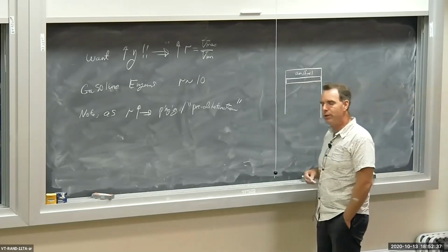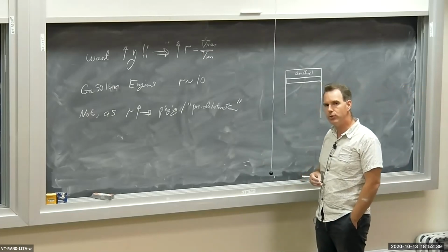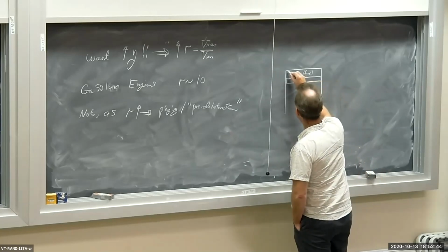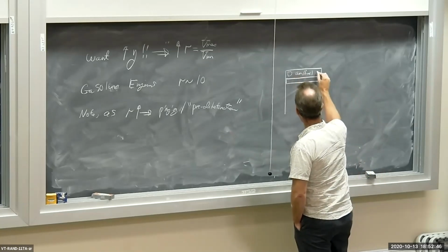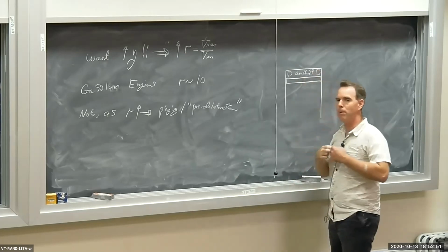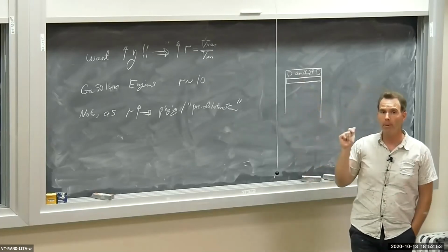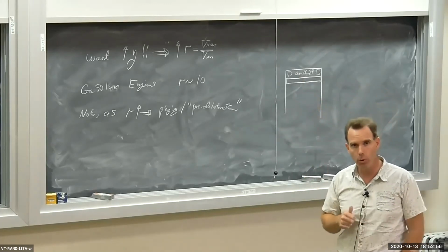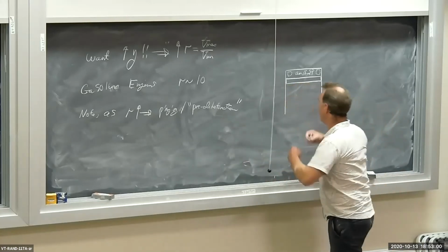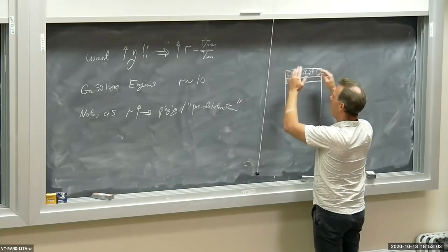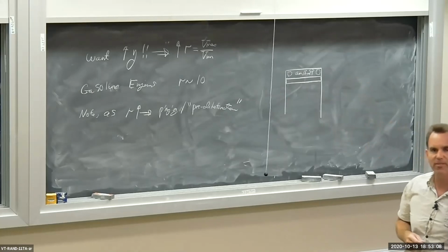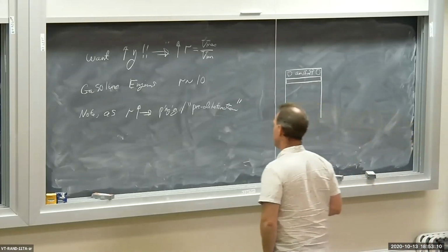If the air-fuel mixture starts to burn or release heat or explode, if you like, in multiple places, so you've got a flame here, you've got a flame there, flames spontaneously starting to burn before the spark plug ignites the fuel, pre-detonation. Then these flames grow and hit each other. The flame fronts hit each other and produce very large pressure spikes.